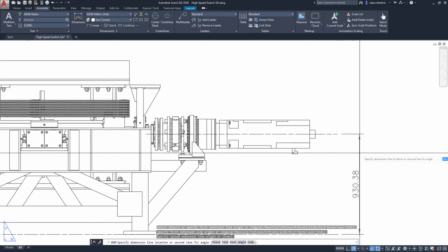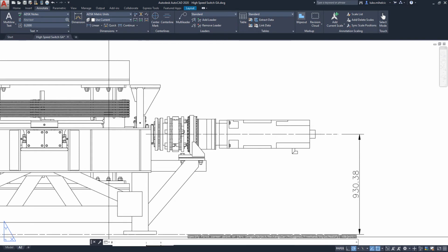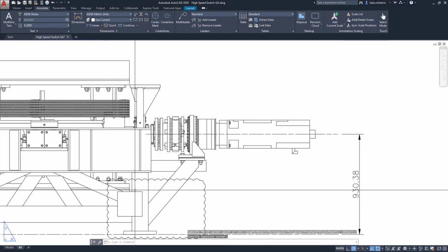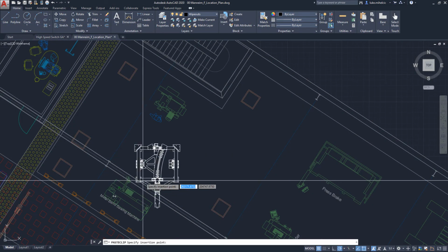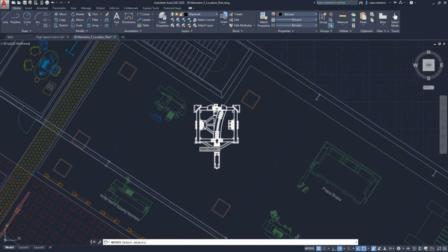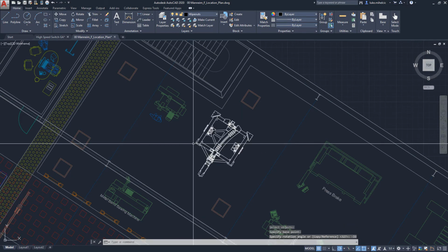This is an ideal workflow for sending data back to AutoCAD so that other users can print, mark up, and annotate 2D AutoCAD drawings. You can also leverage the blocks that are created inside of this DWG file for inserting into other drawings. Keep in mind, this is not associative back to the original file. Only the original DWG file remains associative with Inventor.